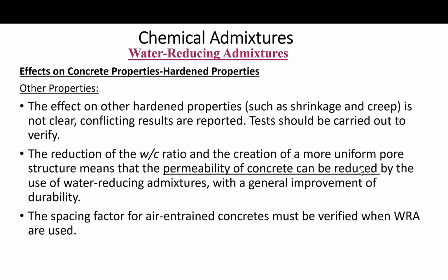But generally, there is no rule of thumb, and there is no clear indication in the literature as to the effect. An increase in the rate of shrinkage is often observed after 90 days of drying, but there is little difference in shrinkage compared to control concrete. Okay, so like I said, really not clear data in the literature.